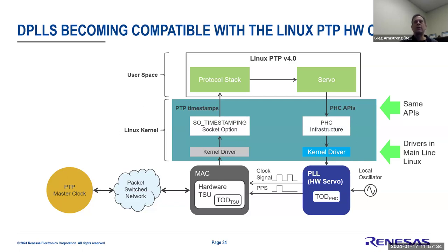And now you start getting something that's a little bit easier to control, because a lot of these PLLs allow you to just simply specify your bandwidth and your target gain peaking, and it controls how it programs the PI filter to make sure it meets those aspects of that. So you don't have to be a servo expert to try to say, well, how do I go and program Linux PTP servo to get the same characteristic? So there's some advantages to the hardware-based mechanisms.